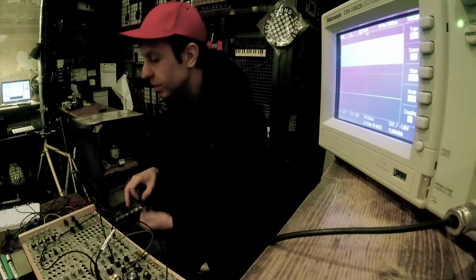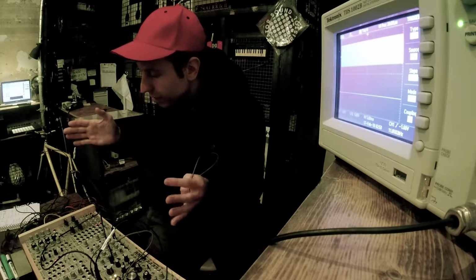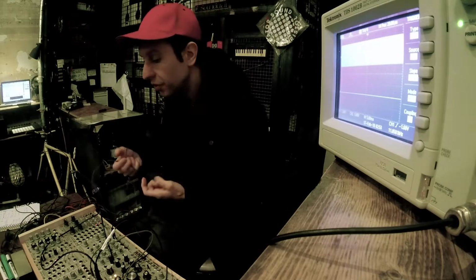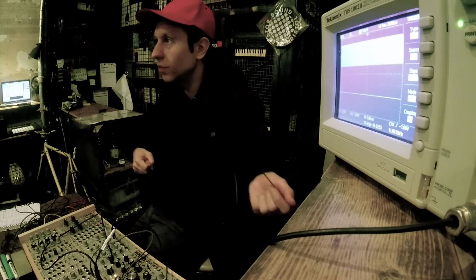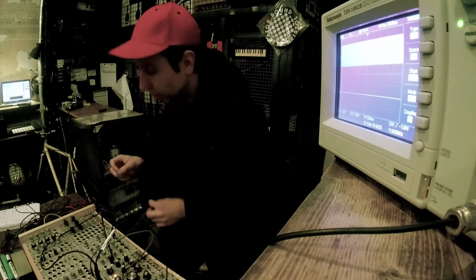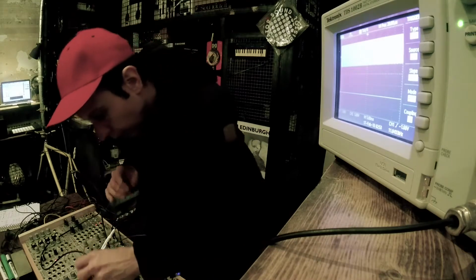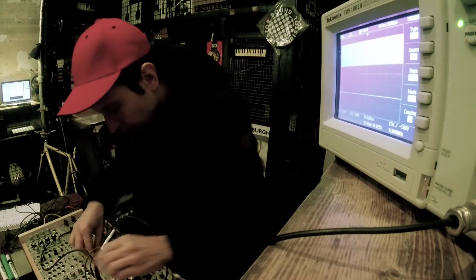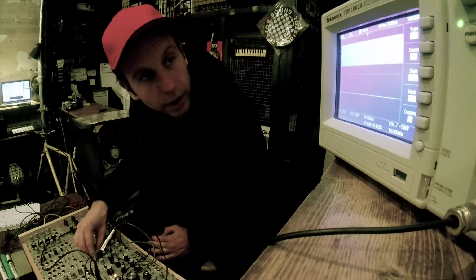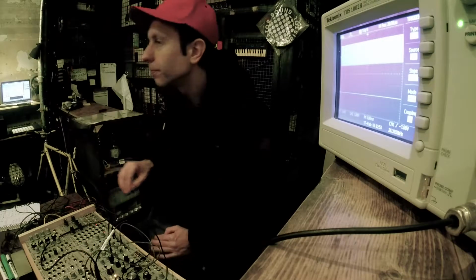We've seen this many times, and almost every module will have a limited range in terms of controlling it with the dial. And if it has a CV input as well, if you really burn the CV input, go plus 12, minus 12, you can normally get beyond the range that is available through just the dial. So let's see if we're lucky with this one. So I'm getting into the CV in here. There we go. So you see, with the dial I couldn't go as high in the frequency, but with this, that's 26K.